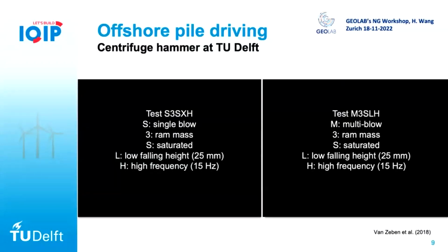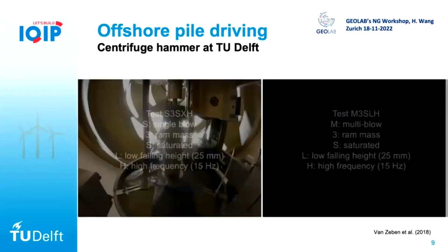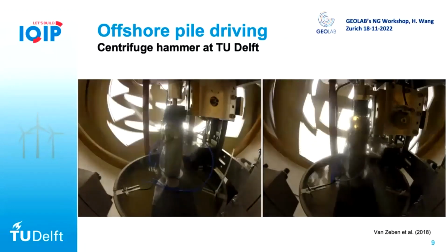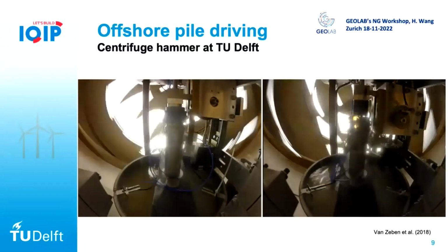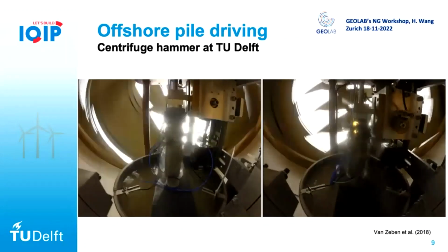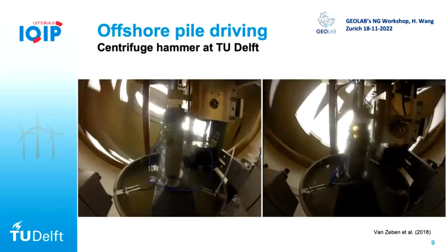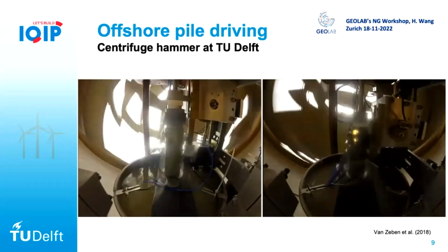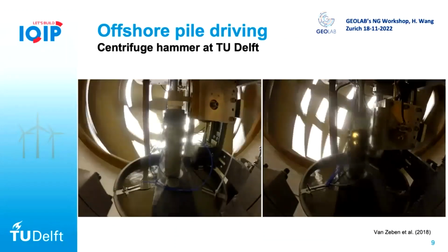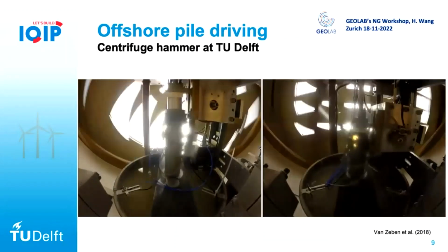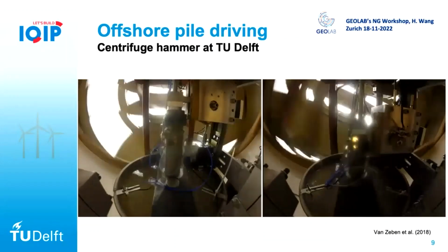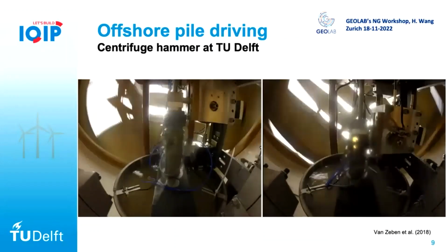And here I show you two tests, and basically because the video from our PhD student Tristan is very nice. On the left is kind of like a single blow test. We lift the ram mass, we penetrate, and we just want to understand how the pore pressure generates around the pile, and how this will affect the penetration depth.